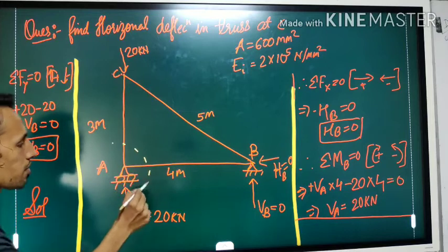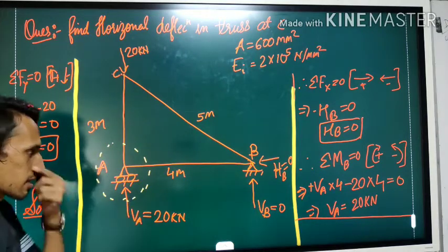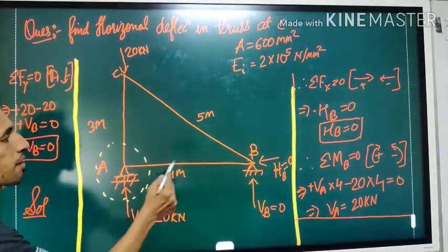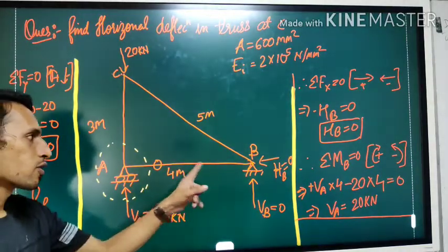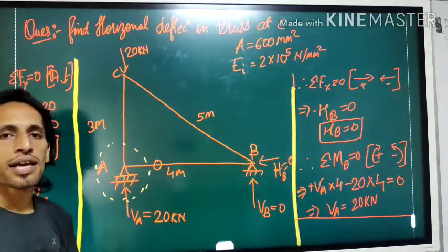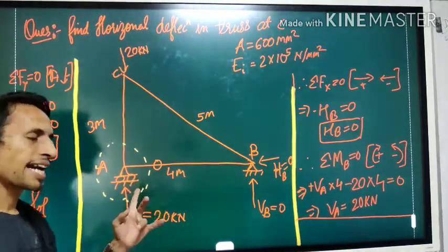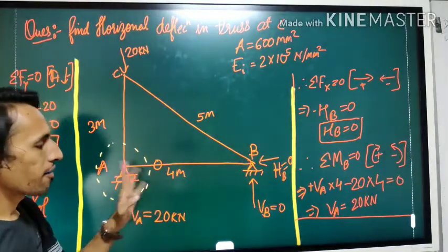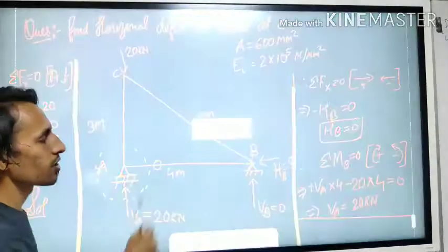You can observe the condition at joint A, and you will realize that this member AB is a zero member force and the value in the member AB will come out to be 0. You may solve it also or you may identify it right now also. So I have identified it and this will reduce my calculation.